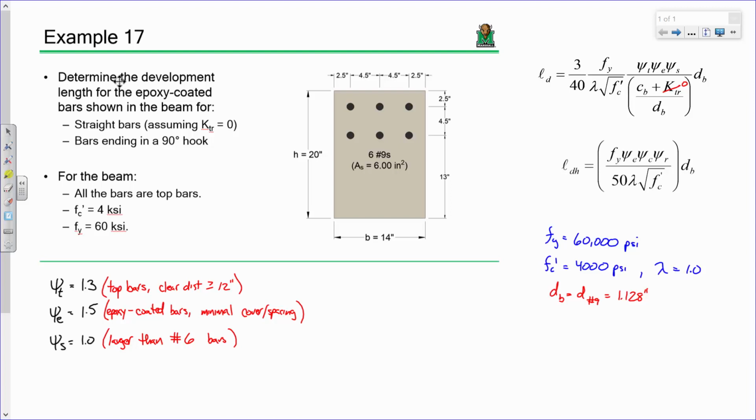All right. Let's take our equation for the development length of a straight bar. Help me out. Let's look at this equation up here. What are we missing? C sub b, right? Now, remember, for you folks in steel design, not even the same thing for beams. Actually today in steel design, we're going to talk about nothing but C sub b. That's our whole topic for steel design today, and it's not the same. Okay, so now we got to figure out C sub b. Now, I'm curious if anybody here can eyeball C sub b and tell me what the value is.